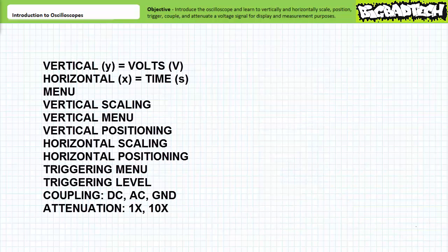Finally, given all the user-adjustable features in an oscilloscope, often the source of errors is not the current user, but rather the previous one. If the previous user happened to set up the oscilloscope with an odd vertical and horizontal sensitivity, position the trace bizarrely, use some abnormal triggering condition, attenuate it weirdly, or perform some other advanced option like inversion or mathematical function, that oscilloscope will appear to act weird, odd, strange, abnormal, bizarre, unusual, and peculiar because, and this is important, it's being told to act that way.